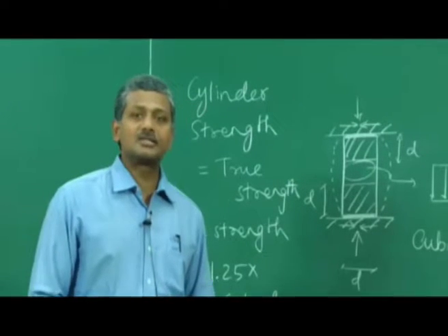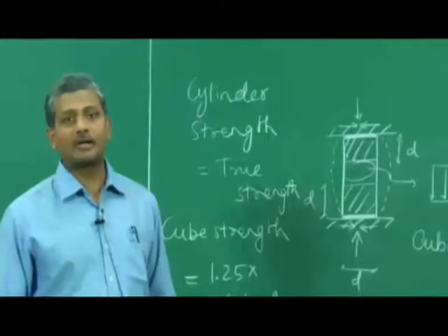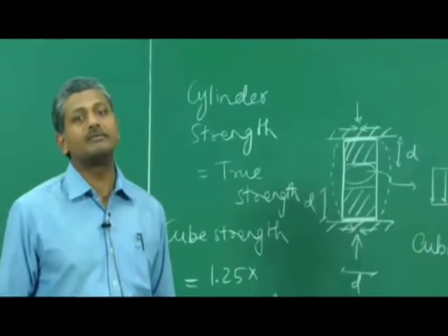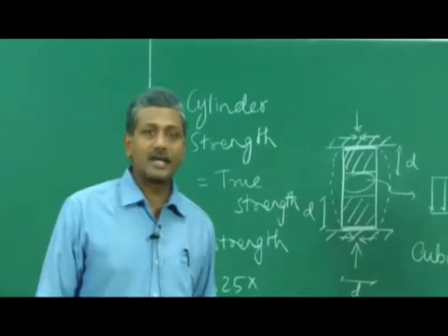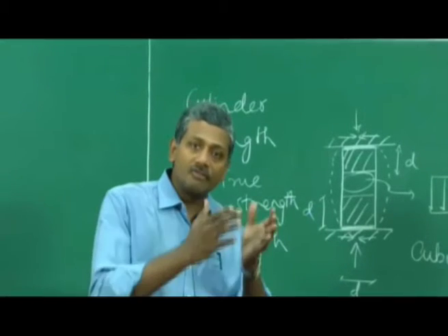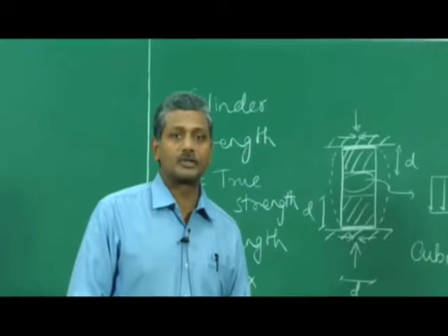and that increase in strength in the case of a cylinder is not felt because you have a zone right in the center of the cylinder where there is no effect of the friction. In the case of a cube, the effect is felt throughout the depth of your cube because all the dimensions are equal, okay.